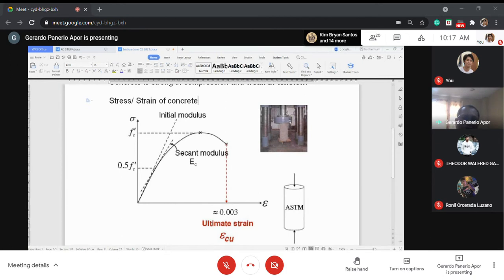slow. So stress is being applied longitudinally, and then little by little increasing it. Then there will be some shortening of the concrete that is recorded. Now the shortening divided by the overall length is the strain, no? That's the formula of the strain. The elongation or the shortening divided by the original length of the sample is what we call the strain. So they are plotted here.